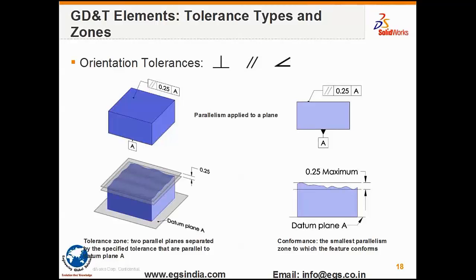Now we need to understand, when we are putting the GD&T controls on the drawing, every additional control is going to cost the company money. So the number of GD&T controls that need to be established on a drawing depends on the design for quality objectives that we are trying to protect, with as little control as possible so that maximization of manufacturing and reduction of the overall product cost is achievable.